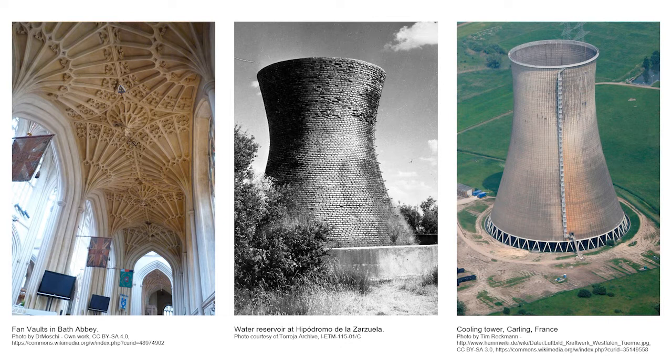Form-finding principal curvature cable nets are also relevant for other non-minimal surfaces which have negative Gaussian curvature. These can be considered approximately minimal and include compressed structures such as fan walls, cooling towers, and others.